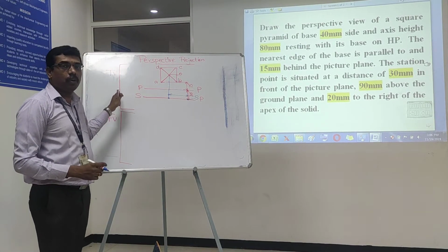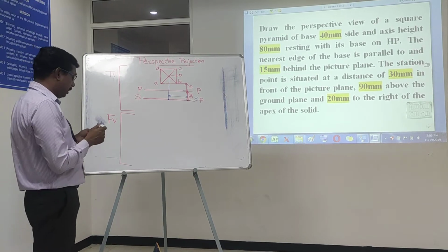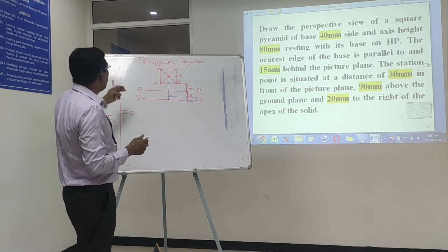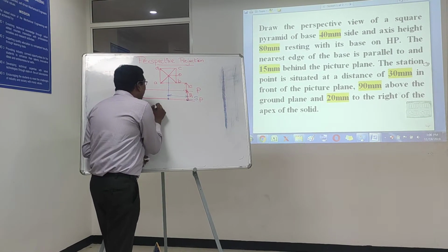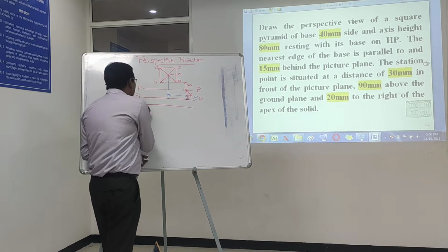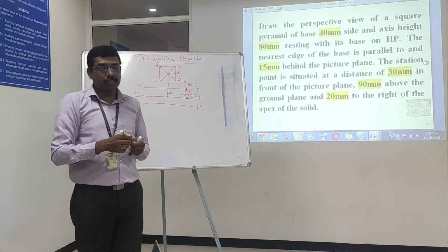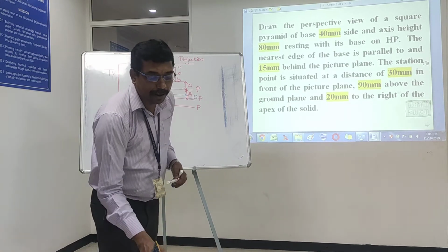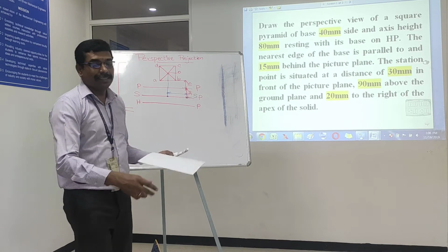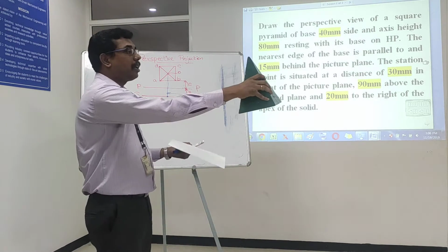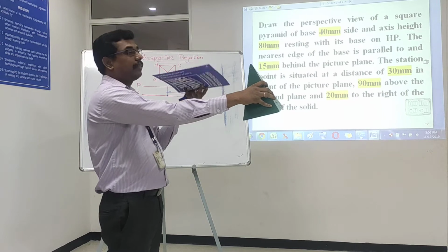Then we have to draw the front view and then make the perspective view of the given solid. Right. And after completing the top view we have to represent another parallel line to indicate the horizon plane in the front view. As you know, the horizon plane is a plane parallel to the ground plane, and this is going to be the solid, and the horizon plane is nothing but the plane that lies at the height of the eyesight of the observer this way.